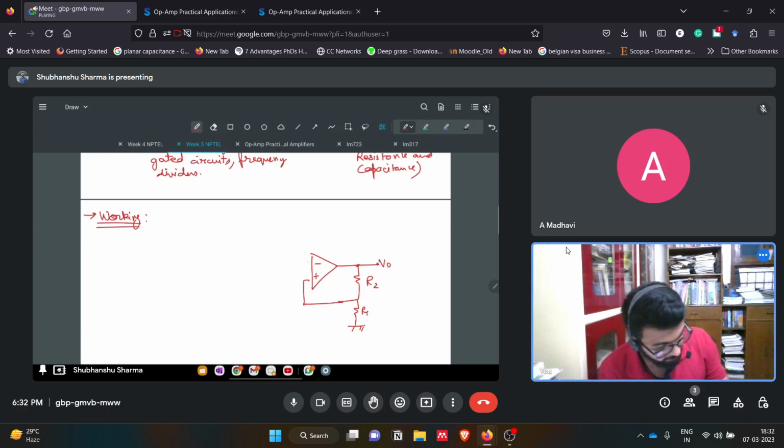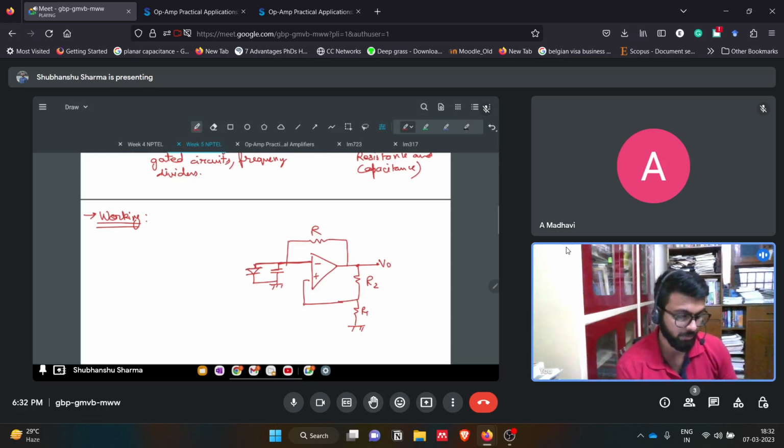And we had this capacitor also in our astable multivibrator, and one resistor also. So till now the circuit is the same. But what changes here, we just attach one diode here. This diode will help this circuit remain in a particular stable state. Because of this diode, we are making this op amp output stay in a particular output state. Now we also have to apply a trigger. From here we will apply the trigger.